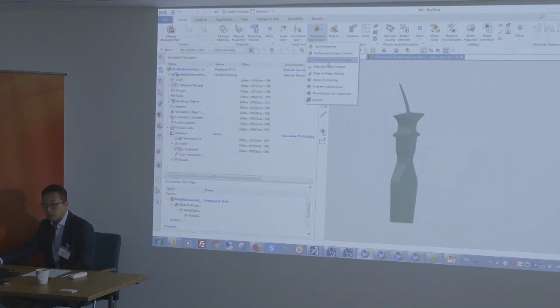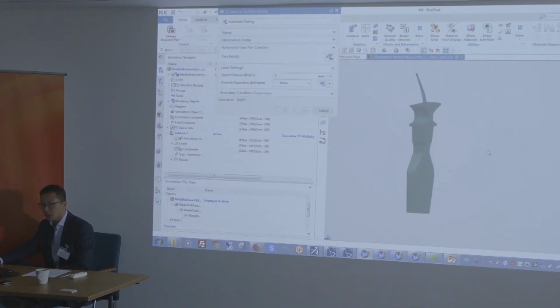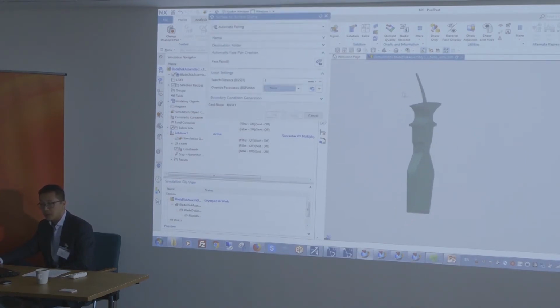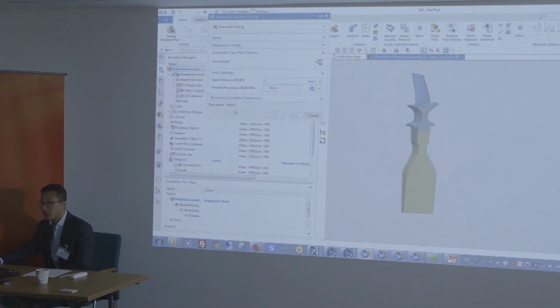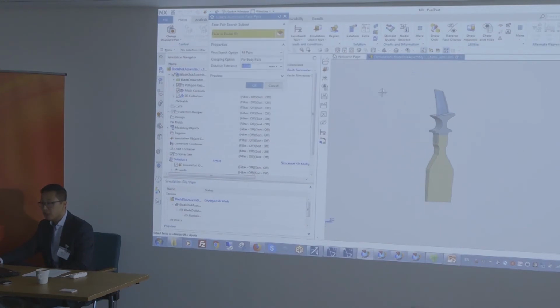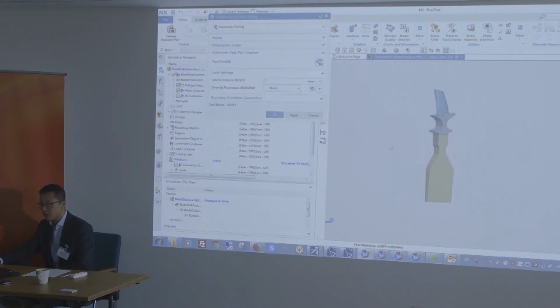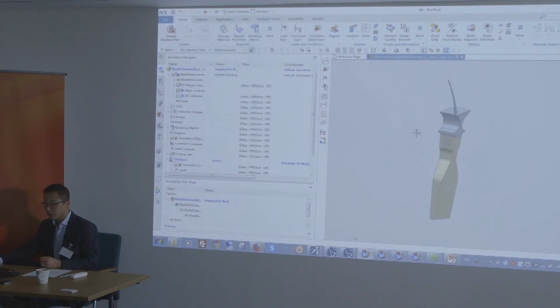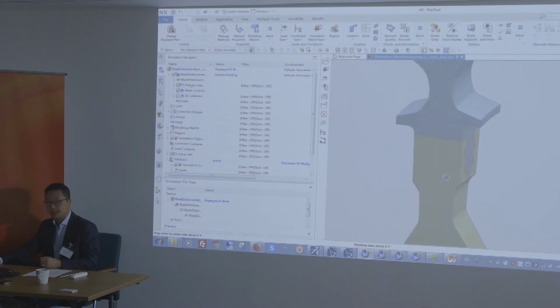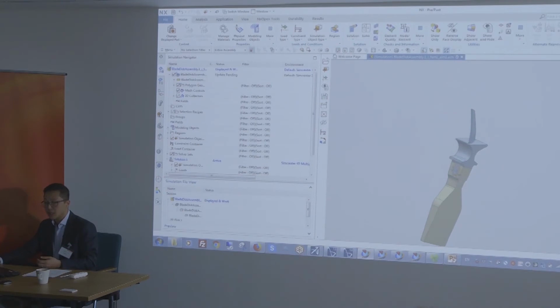In that case, what I could do is a simple surface-to-surface gluing. Let's say I want to glue the elements from the blade to the disc. So what I'll do is I'll just hide the mesh and use our automatic detection tools to find all the faces that are physically touching each other within a certain tolerance. So we don't need to specify the faces for that glue connection. Right? So we can just directly create it, and you'll see all the faces have been detected. Okay. Now what you'll want, of course, is to have those associative to the model. So that's one way of creating connections.